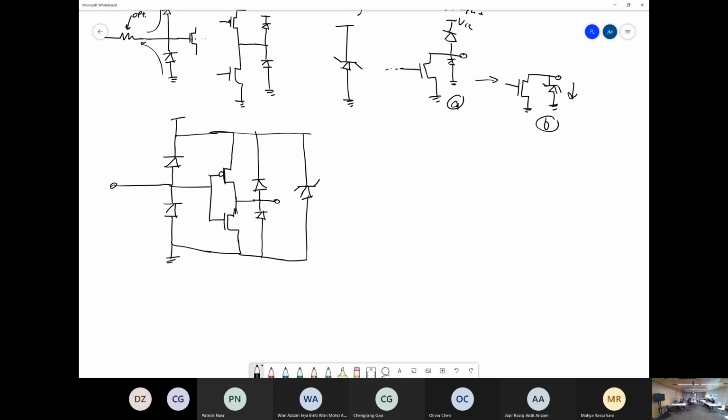Okay. So this is what a typical basic inverter with an ESD structure would look like. Let's say we get a positive pulse, a massive positive spike there. What would happen is it flows in, where would it flow? Up. Now we have two diodes here, a regular diode and a Zener diode. Zener diodes, as I mentioned, are designed to break down at a certain voltage, typically a lot less than a regular diode. So where would it flow? This branch here or this branch here? Branch 2?